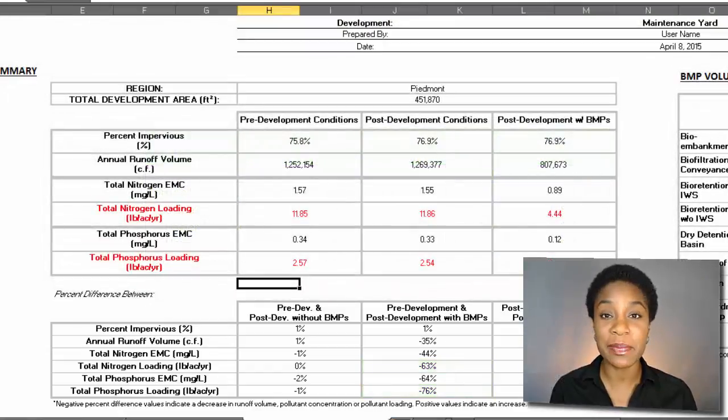In this brief example, we did not adjust the size of the BMPs when we changed the BMP type. In reality, the footprint of a BMP will likely change if the BMP type is altered. Changes in the BMP area would then need to be entered in both the Water Characteristics tab and the BMP Characteristics tab.